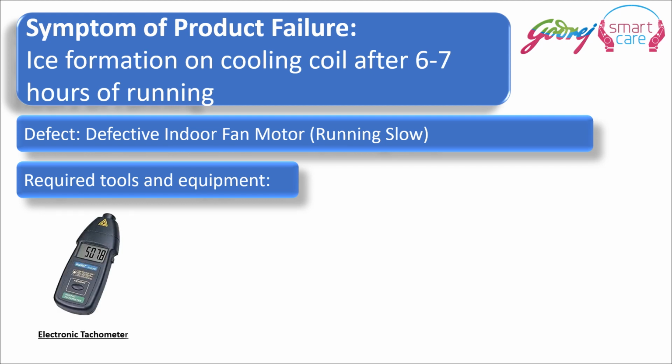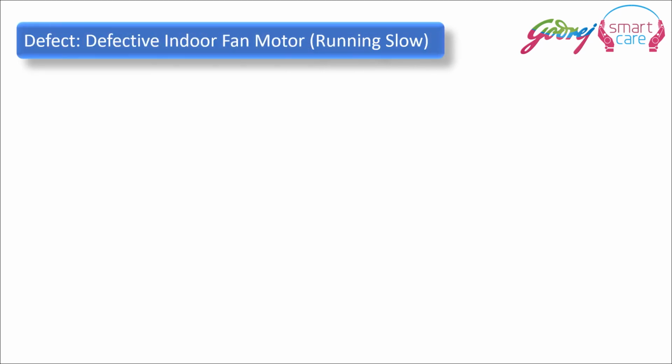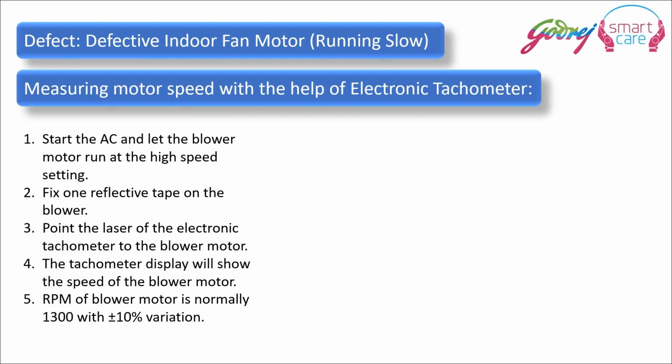Required tools and equipment are an electronic tachometer and a clamp meter. To measure the motor speed with the help of the electronic tachometer, start the AC and let the blower motor run at the highest speed setting.